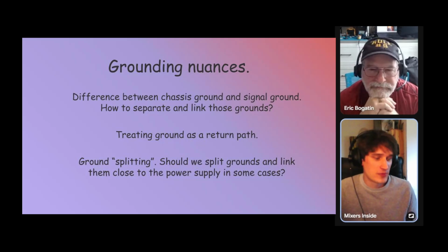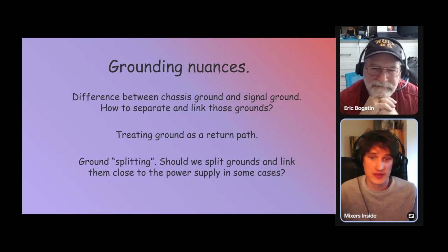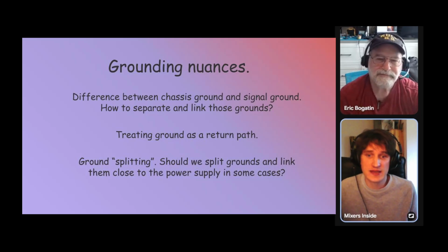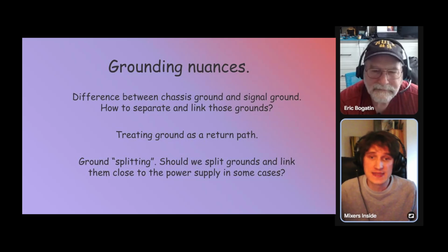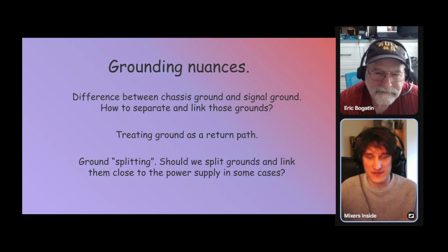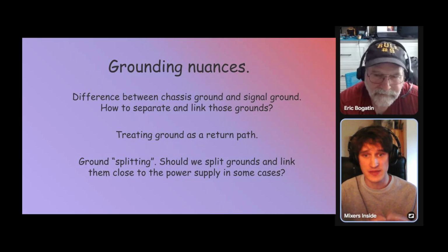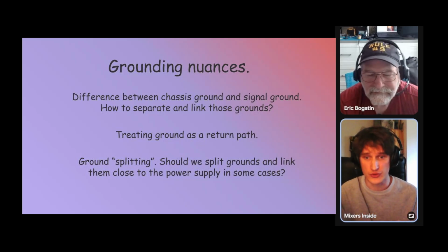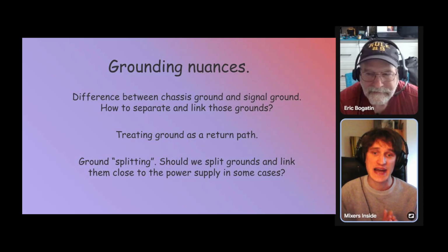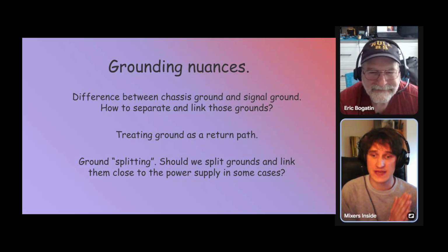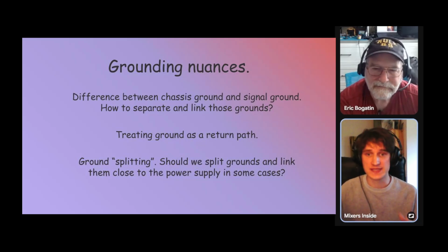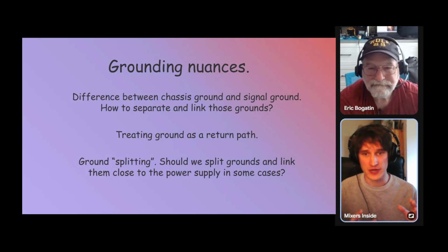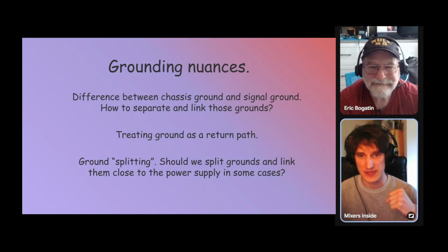But from the empirical perspective, it's a real-world example. A couple of years ago, I designed a phono preamp, and this phono preamp is something very sensitive. There are some signals flowing in the millivolt range, and at the same time, I decided to power this phono preamp with a power supply based on a voltage doubler. And this power supply with a voltage doubler caused some really serious currents charging the capacitors.